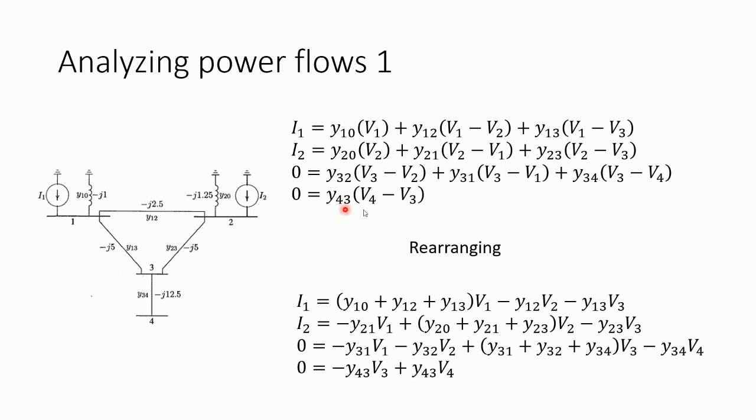The reason we write Y34 in this equation and not Y43 is to be consistent with our derivations of the equations, because when we look at bus number 3, we want to be consistent, so we look at the admittance from the perspective of bus 3 when we are deriving equation number 3, so that all the terms, especially the admittance, start from bus 3 to other buses, and the same concept is applied onto other buses as well.